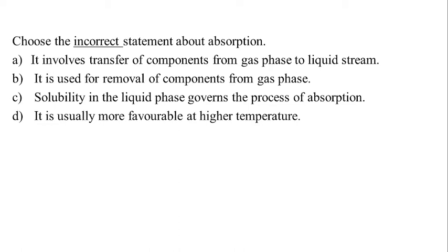The first question is: choose the incorrect statement about absorption. Absorption involves transfer of components from gas phase to liquid phase. It is used for removal of components from gas phase. Solubility in liquid phase governs the process of absorption. It is usually more favorable at high temperature. So, which of these is incorrect?